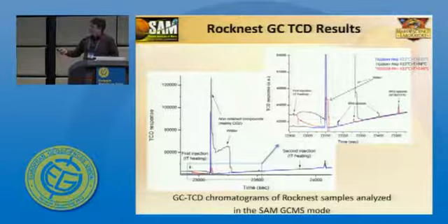And this peak is due to a big contribution of inorganic molecules, meaning mainly CO2 and also SO2 present in the sample and in the atmosphere. And the third inorganic molecule analyzed here is water. We can see that from one sample to another, there's a big difference in water content, which can be quantified with the TCD, and which is difficult to quantify with GCMS analysis.